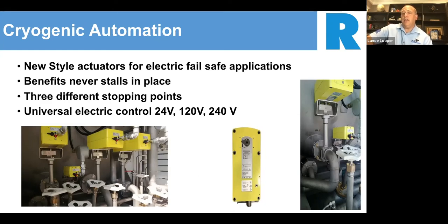What's unique about this actuator is that it incorporates a spring built into the actuator, and it will fail closed. A lot of times people think of electric actuators, unfortunately, when the power goes off, they're stuck where they're at. So they don't go to a fail closed or a fail open position. These actuators actually do that. They were designed in Germany. They've been out in the industry for at least 8 years in the cryo world, and I have not had one problem. They are rock solid products. They work very well. Very unique from an electricity standpoint.